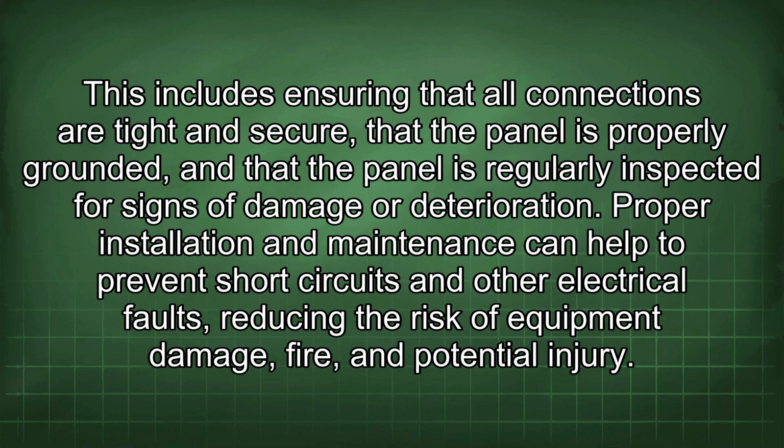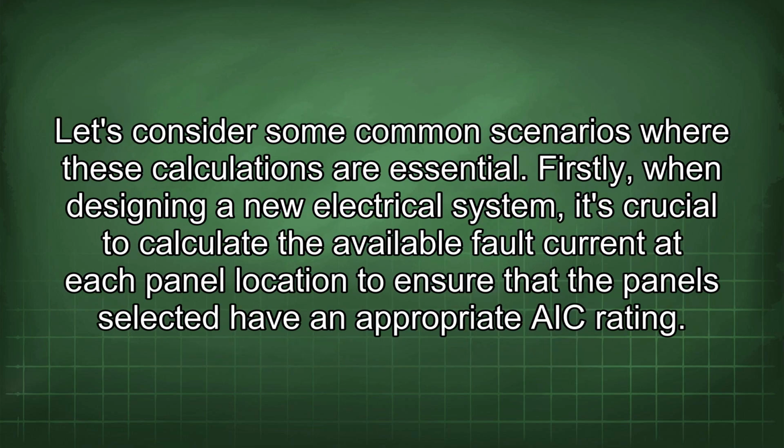Let's consider some common scenarios where these calculations are essential. Firstly, when designing a new electrical system, it's crucial to calculate the available fault current at each panel location to ensure that the panels selected have an appropriate AIC rating.